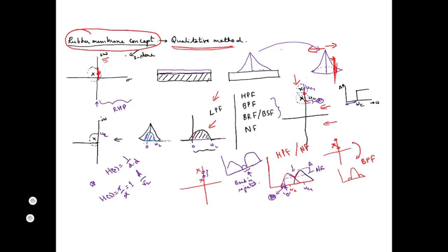Okay, and when we move this zero point away from this frequency axis, slowly we'll be getting that the amplitude is increasing. So we are having this kind of thing. Suppose over here you are having this frequency axis. What is happening if I am moving like this? What is happening in this axis? It is increasing, right? Similarly, if I move the zeros in this way, it is again increasing. Right?